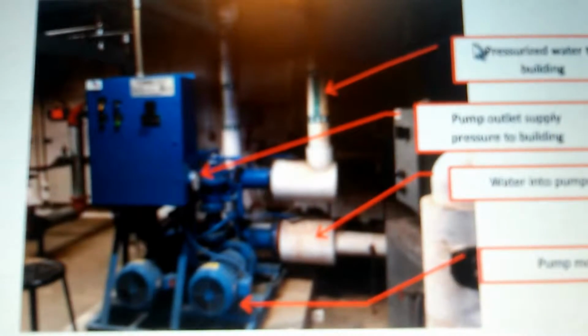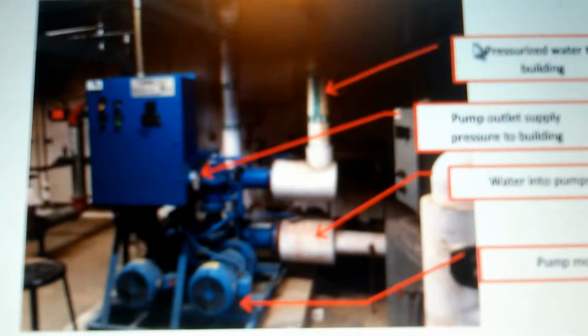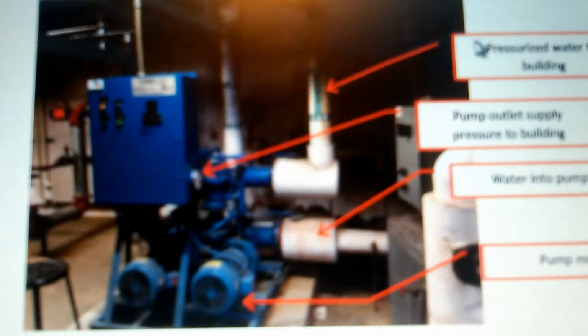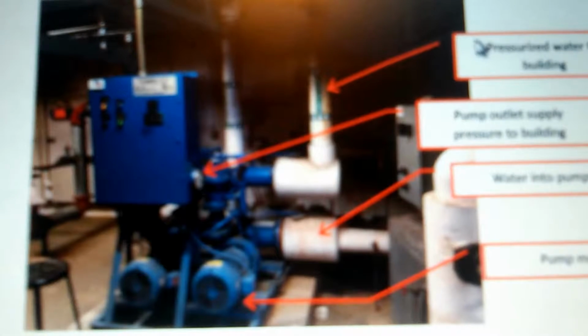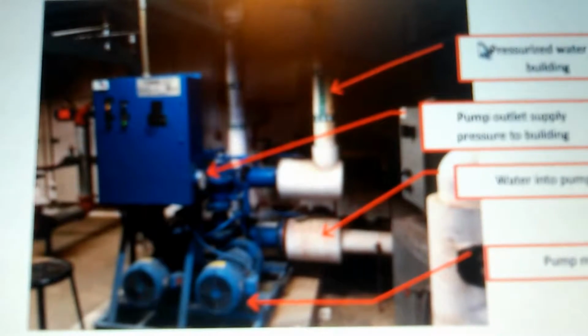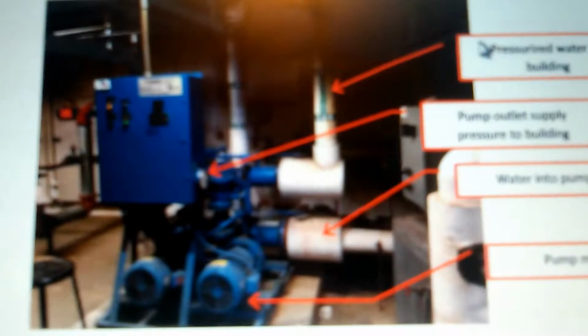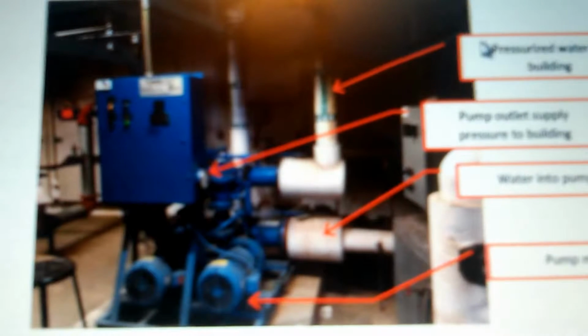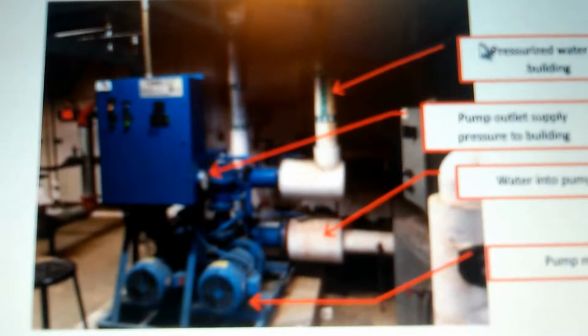And also, the 70 psi does not go directly to the sink. As you know from Bernoulli's, there's going to be a high pressure drop as water travels up in altitude, going from the first floor to the third floor. That's a 20-something meter increase in height, and it changes the pressure to as low as 40 psi once you get to the sink.